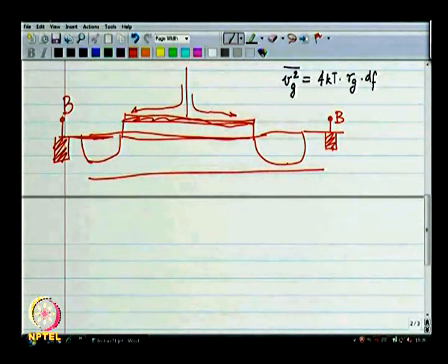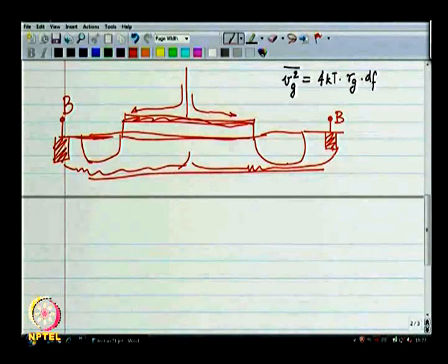Suppose you have put a ring of body contacts around your transistor. That is called a guard ring, just by the way. It is good to do that because that reduces your substrate resistances, we will see how. So the body sees a resistance which is marked by the resistivity of all of this; it is a distributed resistance.